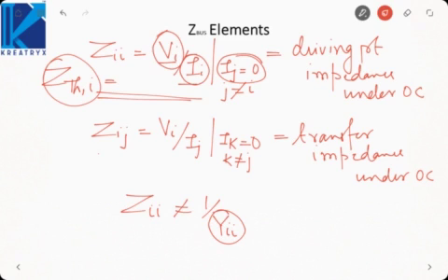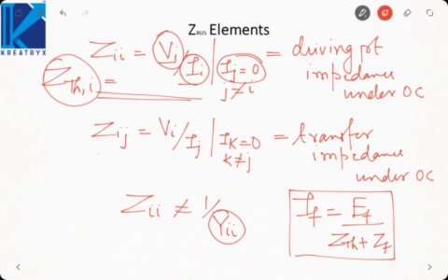Okay, so that is how it is used in fault analysis, because the diagonal elements of the Z bus matrix are the Thevenin impedance at that bus. And as I told you, in fault analysis, to find the fault current, we need the Thevenin impedance and the fault impedance. Fault current is equal to EF by Z Thevenin plus ZF. Okay, that is how.